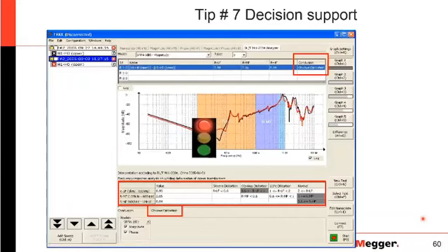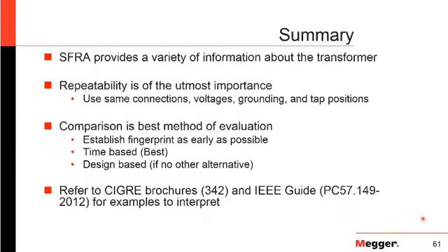But being a sensitive test, repeatability is really highly important. So you want to make sure you're always connecting the same voltages, good grounding practices, you're noting the tap positions, and you're testing in the same tap positions as well. And really, comparison is the best method for evaluation.